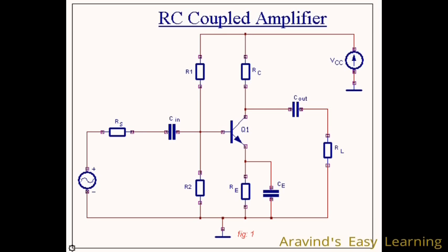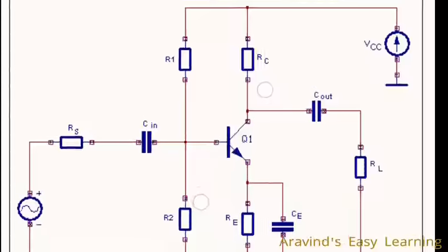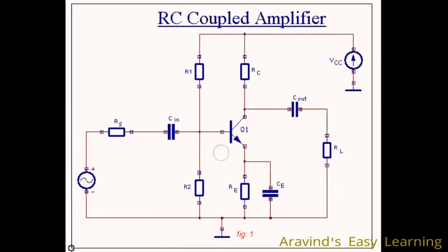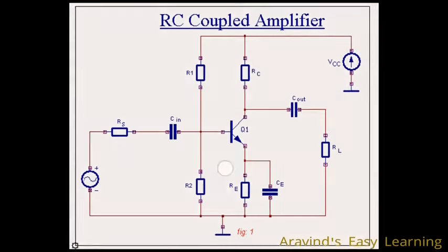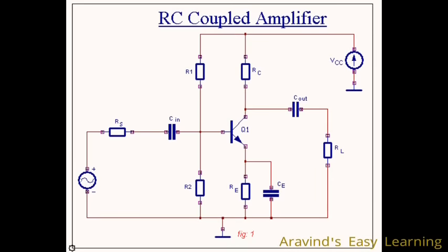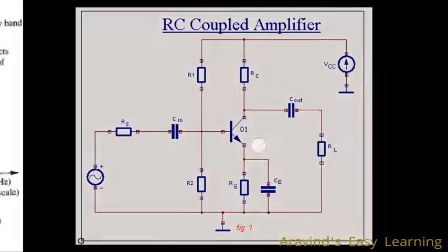We only need to amplify the signal. We do not have to amplify some noise that might be present as DC in the input. Also, if we allow the DC to enter, it might affect the biasing of the interior part where voltage divider biasing is used. So it is extremely important that any other unknown DC doesn't get inside.